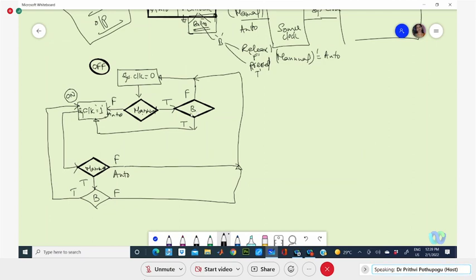If the button is released, it will be resetting the clock. If it is pressed, it will be initiating the clock. Then how much duration it will be initiated will be again checked for the button position. If it was in auto mode, directly after that oscillatory frequency, it will reset this part. If it is in manual mode, what happens is this will be checking for the releasing of the manual button. If it is released, it will be resetting the system.